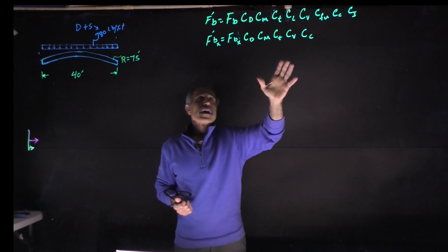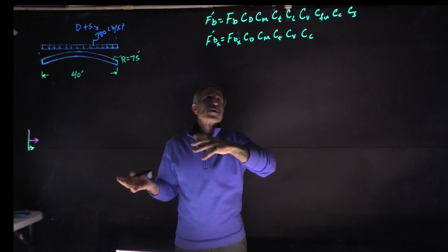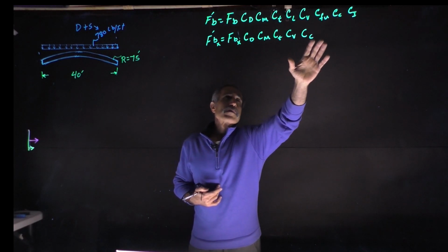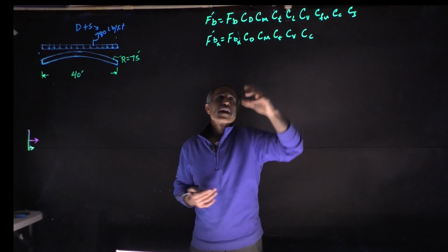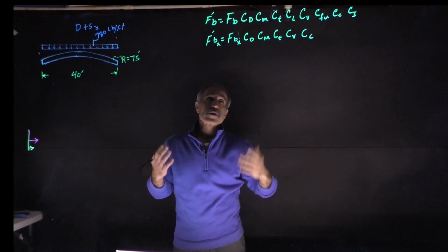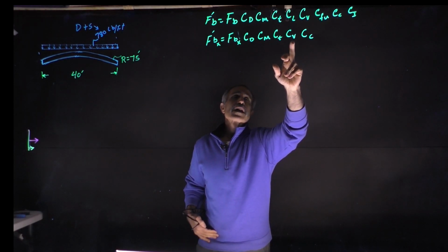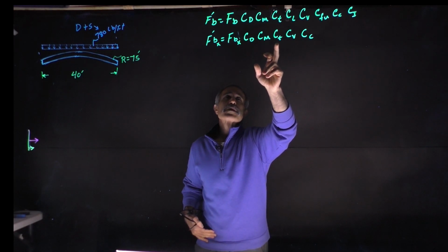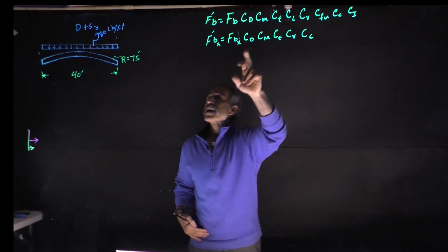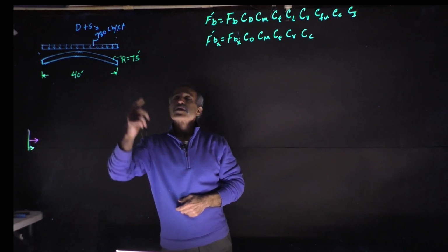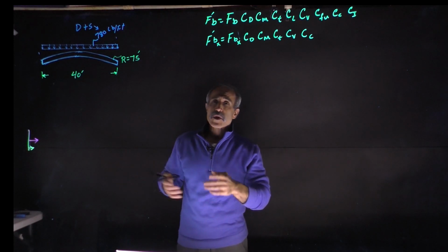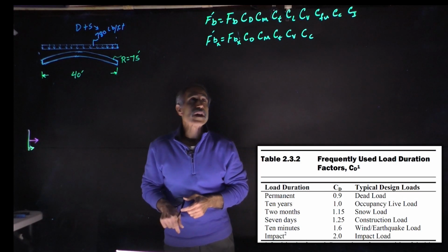Not all of these are going to apply because of the condition you have for the indoor. Some of them are going to be unity, especially CL: a roof beam has lateral support, so it becomes unity. Then we're going to worry about the curve factor, size factor, CT, CM, which is basically 1, and CD, because of the snow load, is 1.15, and you can look up the spec section 2.3.15.